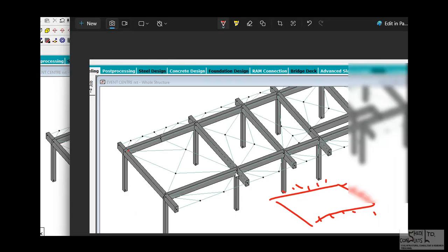Typically, for those who are conversant with plastic analysis of structures, you know that yield lines form at the boundary edges of support. So the yield line forms along supports. That's one of the rules. When a slab is failing, yield lines form at the location of plastic hinges.